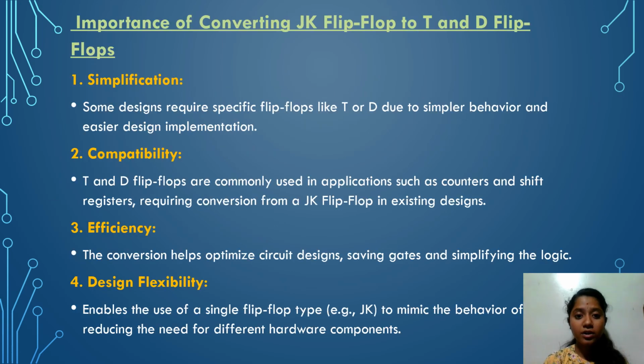Now coming to the importance of converting JK flip-flop to T and D flip-flops. So the first important point is simplification. Some designs require specific flip-flops like T or D due to simpler behavior and easier design implementation. And then for compatibility, T and D flip-flops are commonly used in applications such as counters and shift registers, requiring conversion from a JK flip-flop in existing designs. Then we have efficiency. The conversion helps optimize circuit designs, saving gates and simplifying the logic.